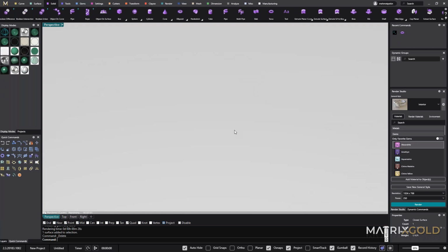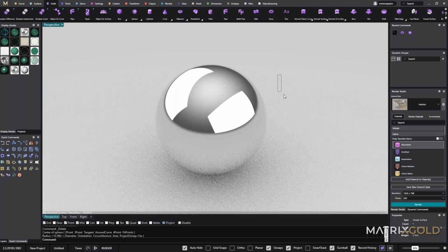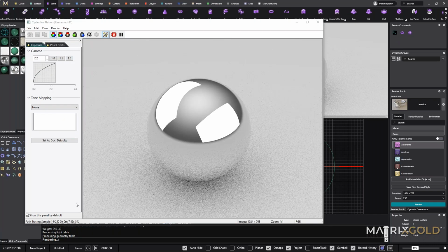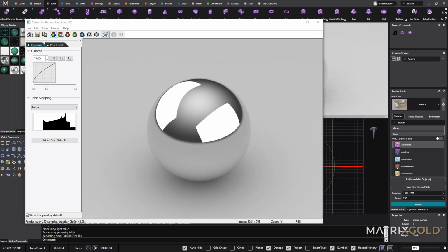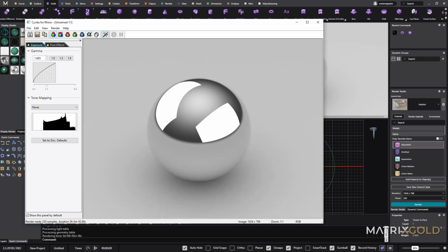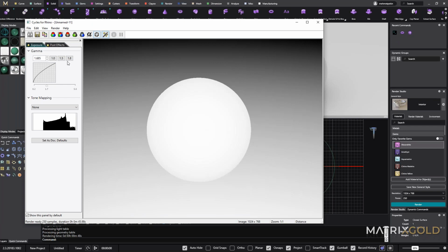Here I will show you when you make something like this. And I'm going to render it. Maybe it will finish in a minute. And you will also select a PNG format. You can pick your models with PNG to make your own ground planes in the backside. You just click on this button, show RGBA channel. And also we have a Z buffer option here.